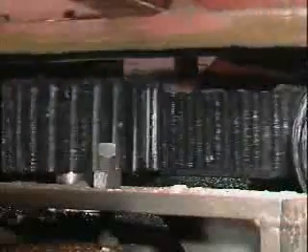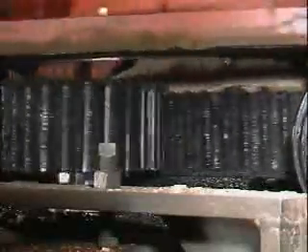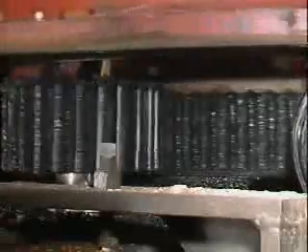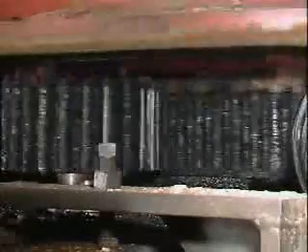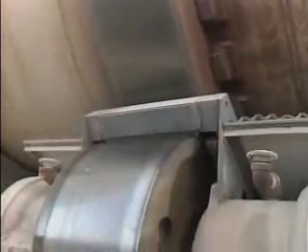An application with relatively high pressure requires a lubricant that won't flow away from where it's needed when the pressure increases, such as when gear teeth mesh. Applications that involve relatively high loads or pressures typically require greases, solid lubricants, or high viscosity oils.